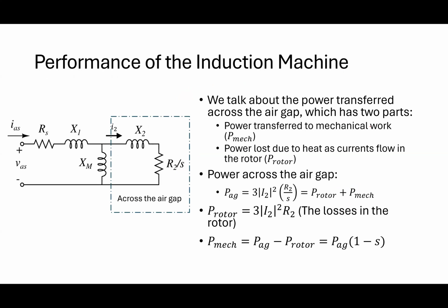All right, so real quick, this is our basic circuit model, right? This is basically a single phase circuit, and this is line to neutral, okay? Normally, when you give ratings on the motor, you give your ratings in line to line. So I think pretty much all the voltages I give you guys will be line to line, okay? And I usually make that clear, but typically you always see them being line to line.